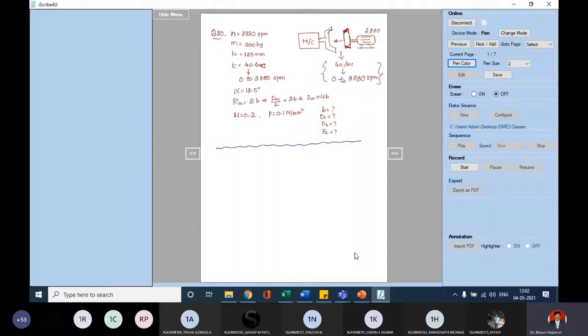Usually we have a notion. How do I know this? Basically, what should I do now? What should I do with these values, M and K? If you solve the problem, we start with MT is equal to 9.55 into 10 power of 6 capital N by small n. This is your torque equation in terms of Newton mm, guys.